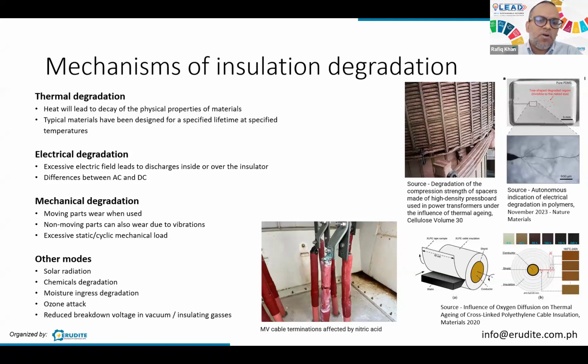But sometimes there are also issues related to termination or bad contacts, and these points have temperature rise. You have also extra loading that can result in temperature rise of the core. We normally say that 90 degrees is where XLPE insulation starts to have its limits.